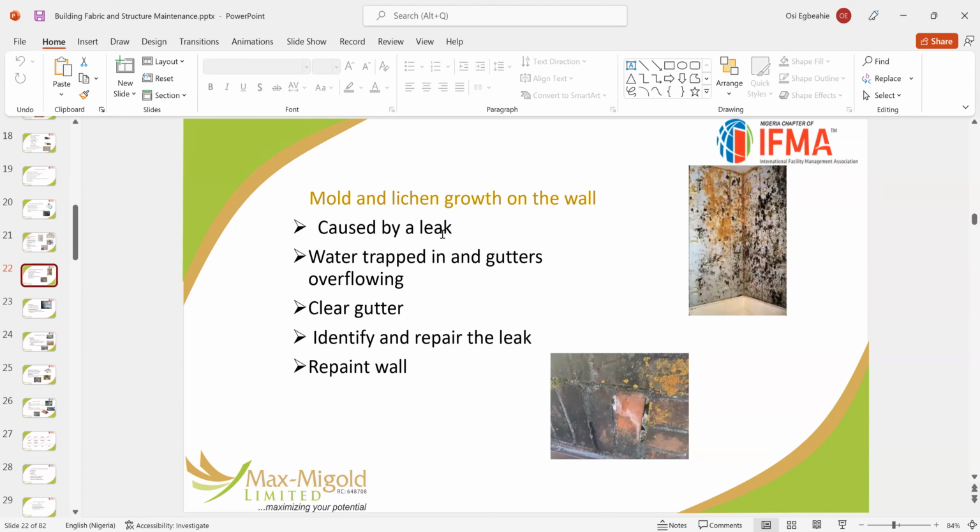When you have mold on walls, it means that there's some form of leakage in that wall. Once there's leakage in that wall, you normally will just find out the cause of the leakage and then try to stop it up. Probably there's a corroded pipe or a leaking pipe, or a blocked floor drain or blocked roof gutter, or the AC condensate pipes within the wall are blocked, so it's not sending water out and it's just busted and started affecting the walls.